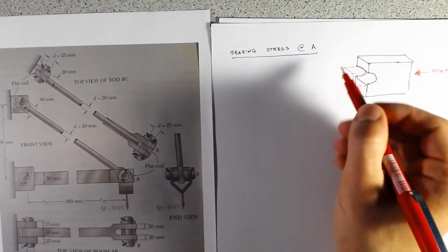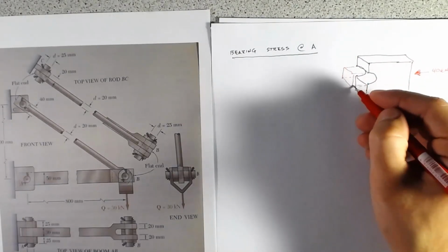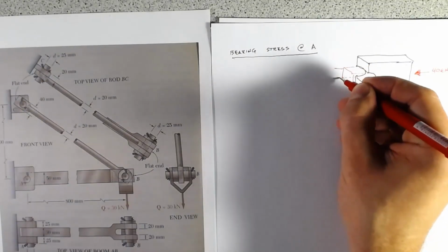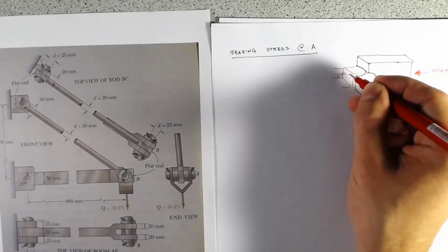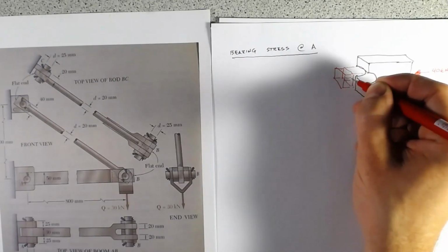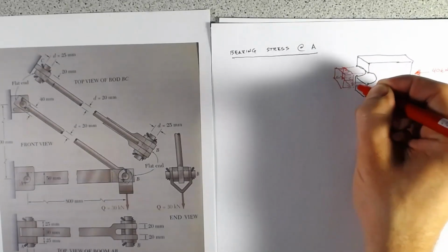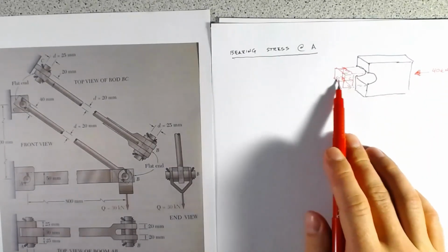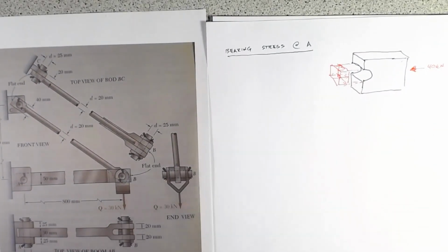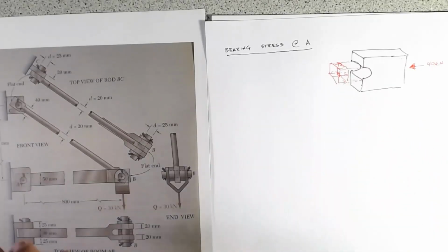And so that means that the bearing is just going to be over the thickness times the diameter. And again, with bearing stress, because we're looking at an average stress, we're assuming that that's going to be an equal stress over that entire area that it acts on. So that's just a nice rectangular stress block there. So cool, we have our load, we have our area, we just need to work out some numbers, and then we know our stress.